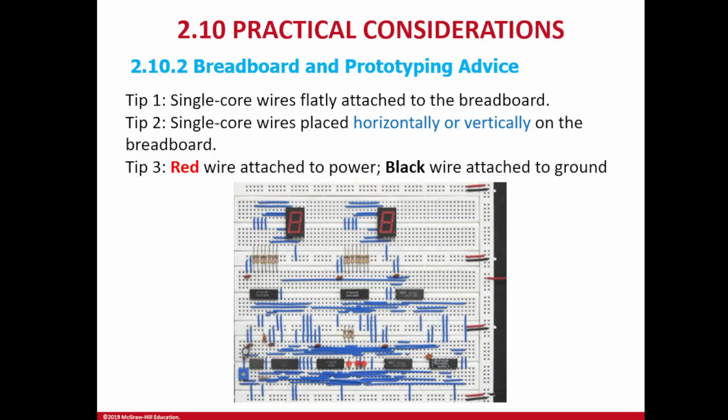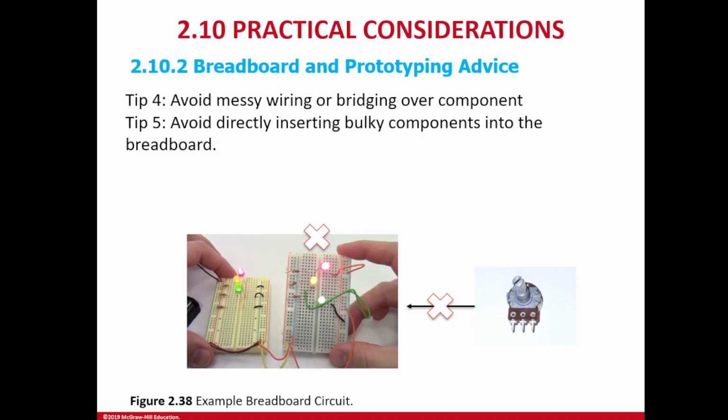For example, some students will connect this wire over the top of the IC to the other point. This is very bad practice. First of all, when you want to take this out, you need to detach the cables, and that makes your troubleshooting more difficult. So don't over bridge. Over bridging is not good.